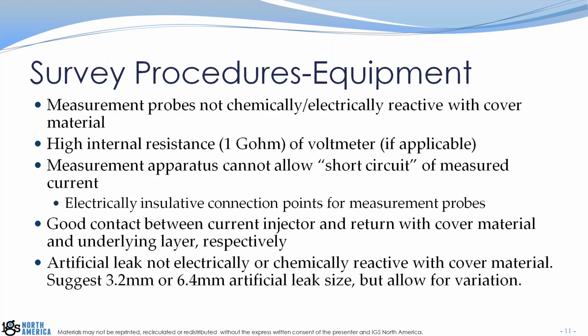The other issue is that it's so conductive that if you have even one location that keeps the material from being isolated, let's say one conductive penetration or one outlet that's full, all of the current will go in that because it's so highly conductive.